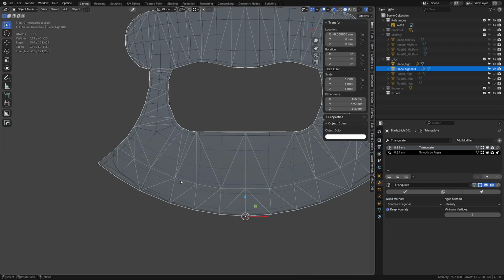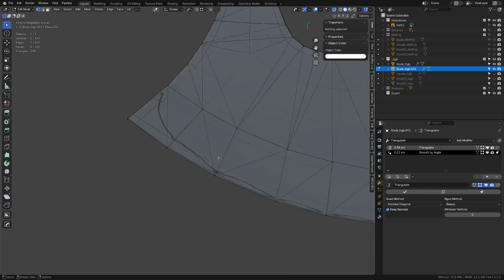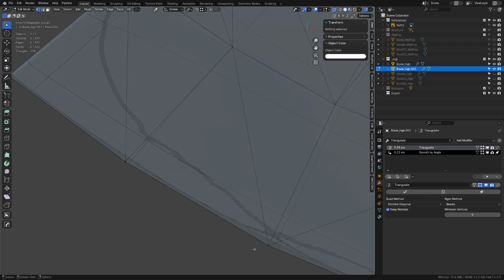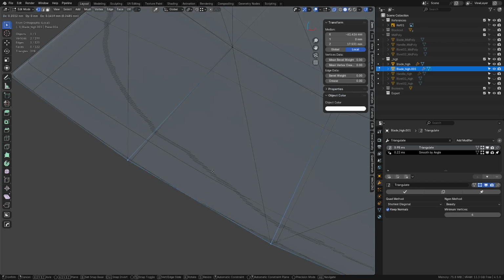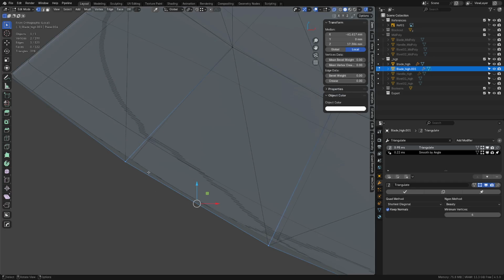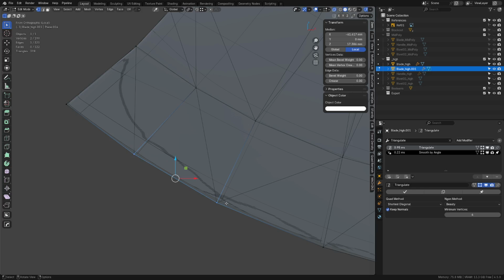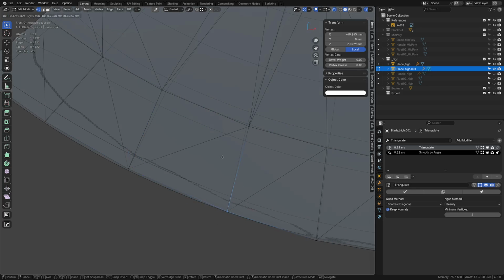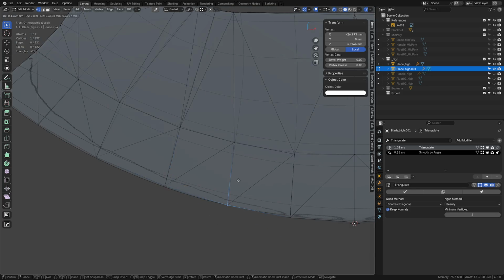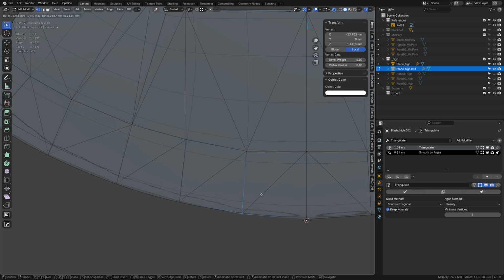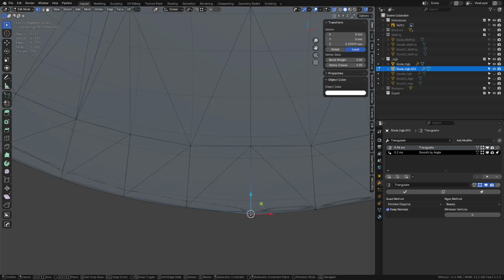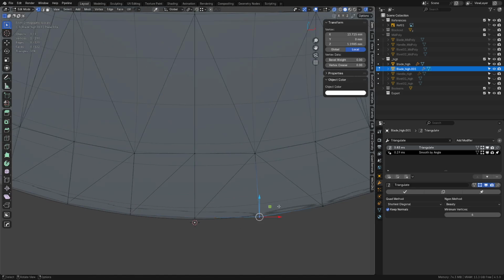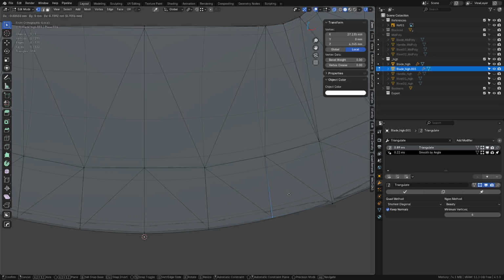So our subdivision mesh is really good and our low poly matches it very well. But one of the issues we will find is that you see how these edges kind of overextend the high poly. When you bake, this is going to create a really dark spot here. This is what happens. So the very tip of the edge when you bake, push the low poly inside of the high poly. Or if your low poly is already UV unwrapped and everything, you can take the high poly and push it over the side of the low poly. You can do one or the other.